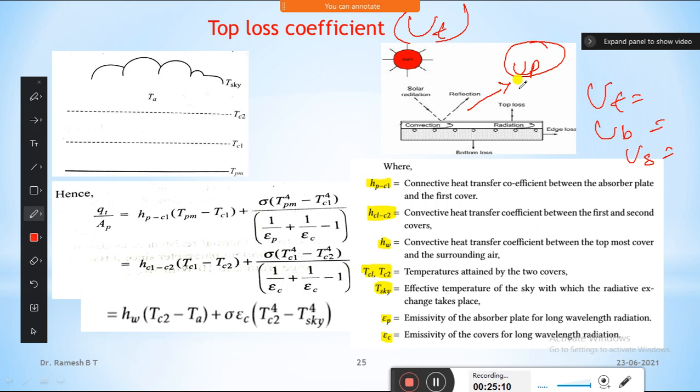It is further assumed that the temperature drop across the thickness of the cover is negligible. That is most important. Whatever the cover thickness may be, more or less, we can neglect the temperature drop across it, because it is very small. And the interaction between the incoming radiation and the absorption in the covers, and the outgoing loss, may be neglected.